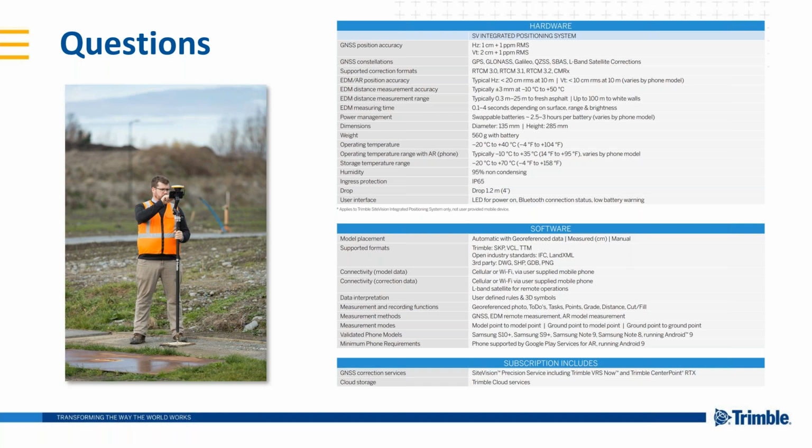What is the distance of the EDM? I think the typical distance for the EDM is out to 25 meters, but best case, we've had it returning distances out to 100 meters. I would caution people measuring out to that longer range, however, because the accuracy with which you're measuring really depends mostly on how still or how steady you are holding the device.